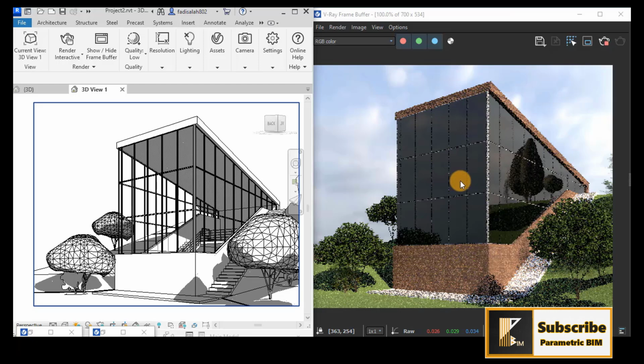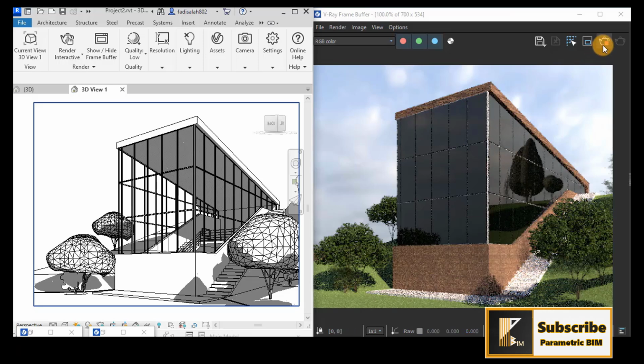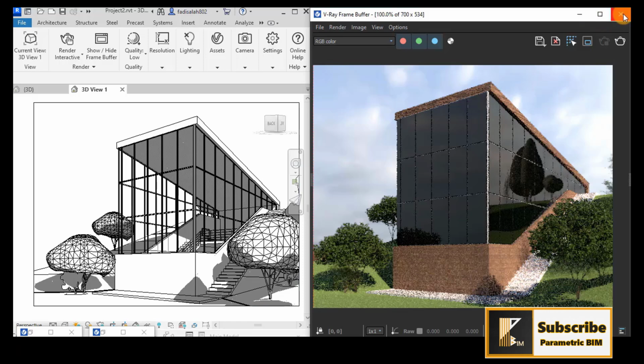The idea behind the materials is that you replace the Revit materials with the Vray materials. So the next step is to use the asset editor and the appearance manager to replace these materials. I will now stop this rendering and try to explain this procedure.